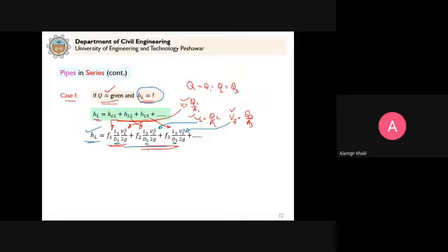And then in the end, you have to verify. You will calculate the Reynolds number and the relative roughness, and then you use the Haaland equation, Colebrook equation or Moody's diagram, and then again you will calculate these f values, and this will continue. The trials will continue unless and until the assumed value of f becomes equal to the calculated value of f. Then the solution will terminate, and those f values you can put here, clear, and you can easily calculate